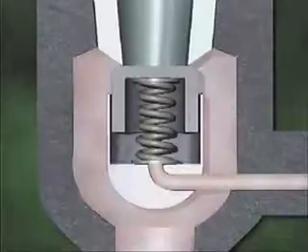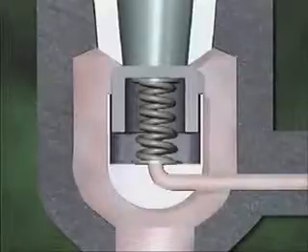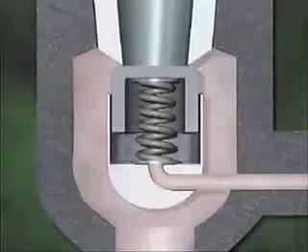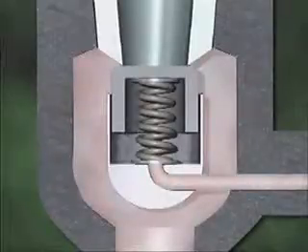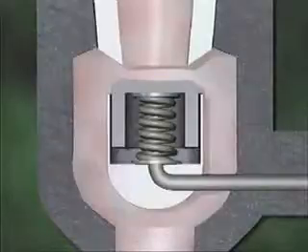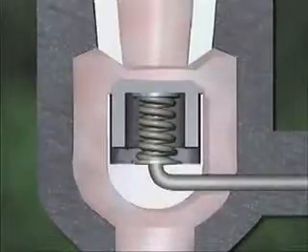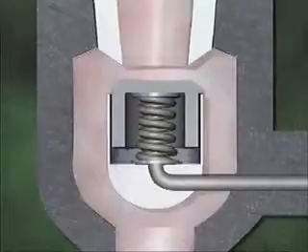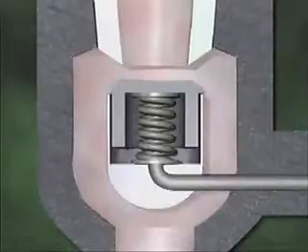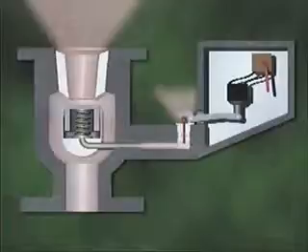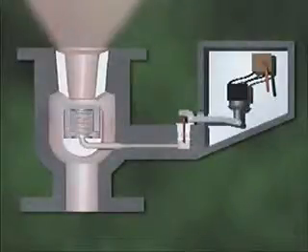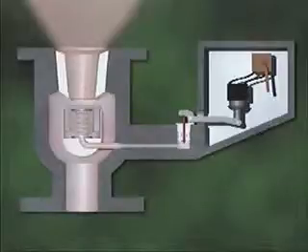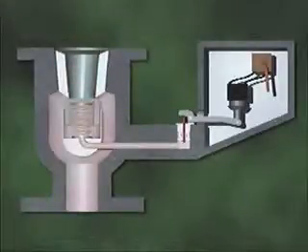The excess pressure that's relieved by the pilot valve comes from below the disc in the main valve. The amount of pressure that the pilot valve is capable of relieving is greater than the amount that could leak between the disc and the disc guide. When this pressure is relieved, the only pressure that remains on the disc is the pressure that's above it. With no counterbalancing pressure below the disc, the pressure above the disc easily overcomes the spring tension, so the valve opens to release system fluid through the outlet above the disc. When system pressure returns to normal, the pilot valve closes. Pressure then builds up again below the main valve disc and helps the spring hold the disc closed.